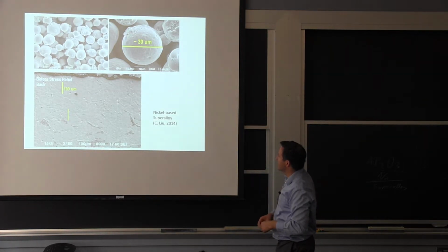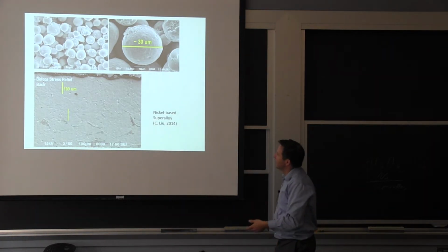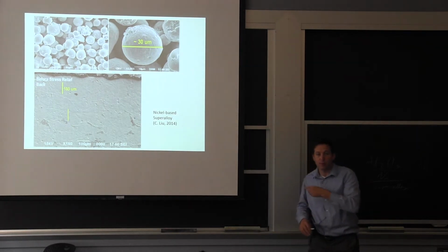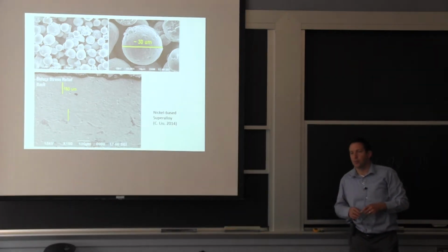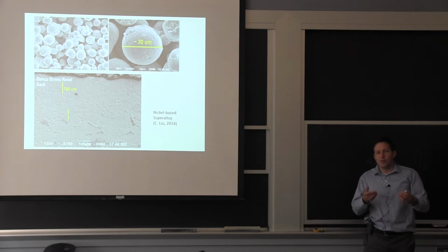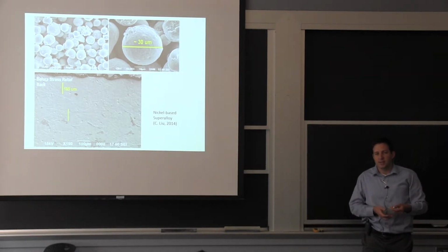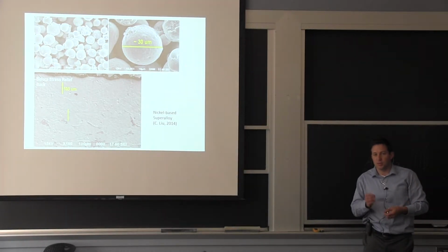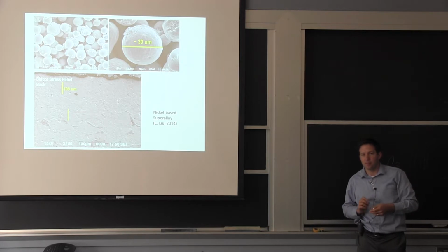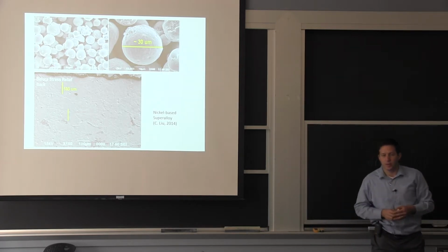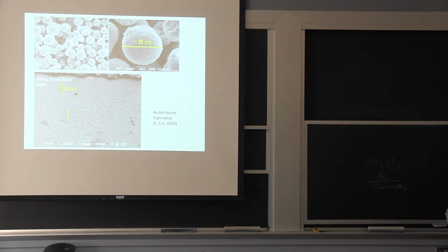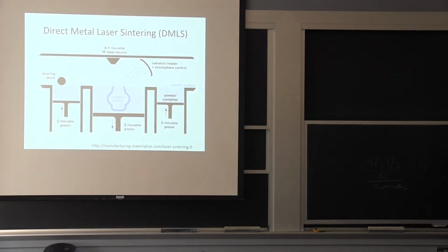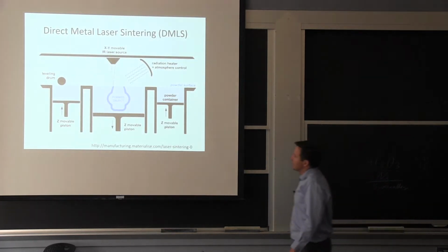You can see you melted at least 100 or so of these little particles on each melted pool. So if I use a smaller powder in this case, it's not going to make much difference. What I would want to do is reduce my melted pool size if I want to make more intricate geometries. So just going quickly, it's exactly like you guys said.